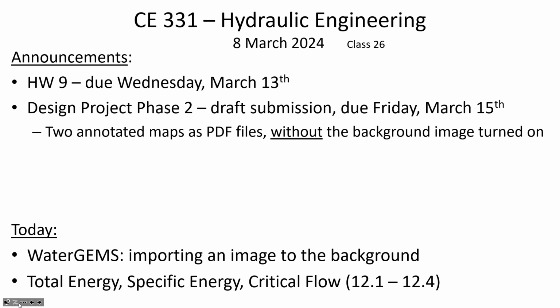What you'll submit for that draft submission on Friday of next week is just 2 PDF files and nothing else. It's going to be a PDF file that has the network under full flow, so the demand being the design demand, and then the same network, same pipe sizes, but with no water being drawn through the outlets. So just to see what the pressures look like under static conditions. I'll show you some additional information about that in just a minute when we do the image importing demo for WaterGEMS.